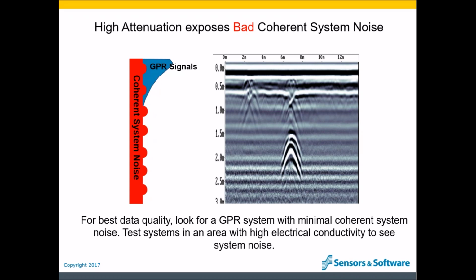I've seen many GPR practitioners interpret coherent system noise as real subsurface reflectors. And as we all know, once you put a colored line on a reflection, everyone believes the interpretation. If you see very flat reflectors in your data, be suspicious. Mother Nature is not like that.